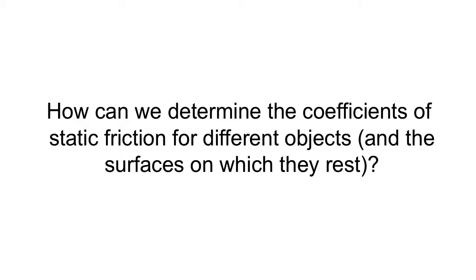We're going to tilt the ramp. What do you expect? If something has a very, very high frictional force, which means it has a high coefficient of static friction, what do I have to do? Do I have to increase the angle more, or will it start to slide at a less angle? Increase more, right? Imagine I put something almost sticky, like tape. I put double-sided tape on this thing, but it wasn't perfect. I would have to lift it almost to vertical before gravity was strong enough to take it down the ramp. Okay? So in this angle is embedded the information about this coefficient.